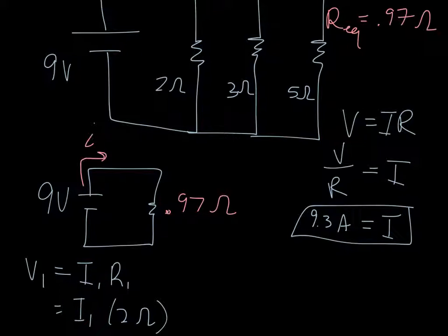Why? Because the voltage is the same across each resistor. In parallel, the voltage is the same across each resistor. Whereas in series, we had to split up the voltage. Now we're going to be splitting up the current in parallel. That's where those laws switch. You have to remember that they switch. So the overall voltage in parallel is the same as the voltage supplied by the battery.